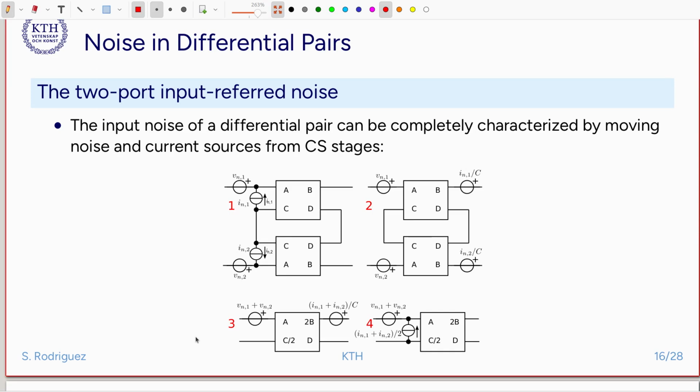In balanced configurations, for instance, in differential pairs, the analysis that we're going to do is very similar to the analysis that we have done for the single-ended amplifier by basic configurations. For the differential pair, we have two transistors that are the same size with the same bias conditions, and when we connect them, both of them will have their input referred noise, as we see here.